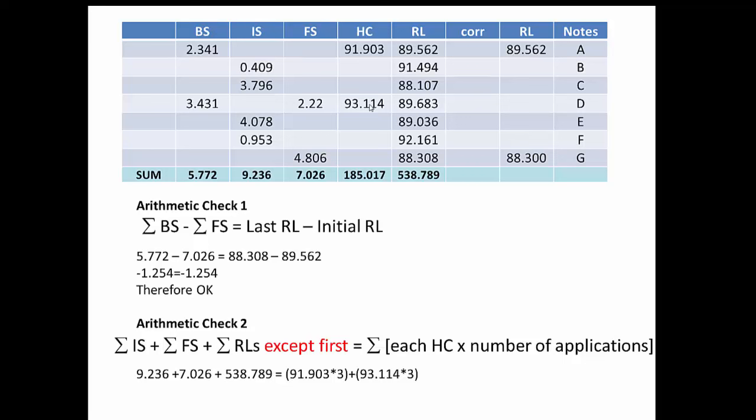And this height of collimation was used to work out the height of this point, this point, and this point. So 3 times each. The first height of collimation by 3, add that to the second height of collimation by 3. Once again, we end up with both sides equal to a number. It doesn't actually matter what these numbers are. What matters is that the numbers are the same. So we're okay.